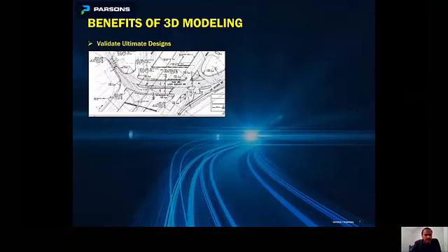So this is another location where we had a cross street that we had to grade the U-turns for the ultimate condition. We just needed to accommodate the U-turn design in our interim condition, and so we had to grade those U-turn areas and then set the bottom of walls and finish grades correctly, considering those ultimate U-turns. And based on the ultimate U-turn profiles, we were able to grade those areas correctly.